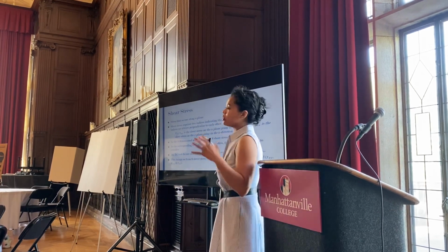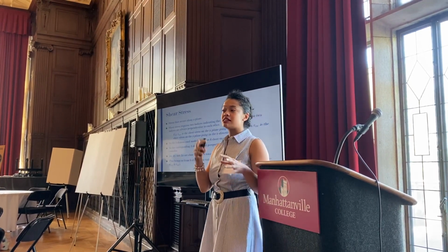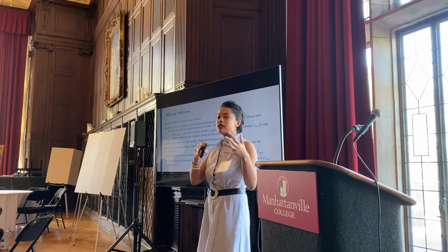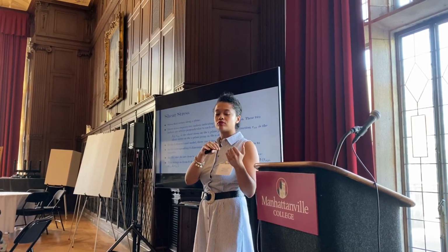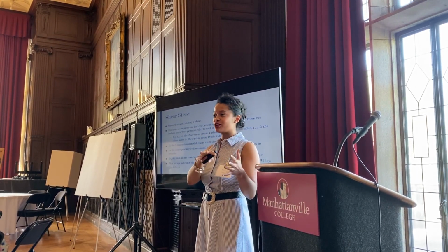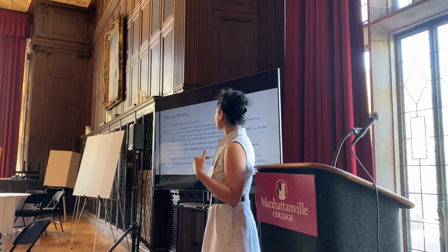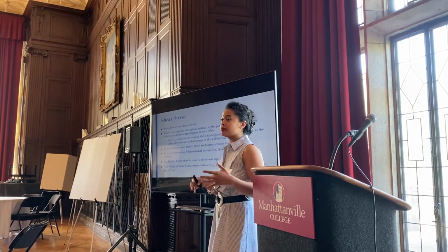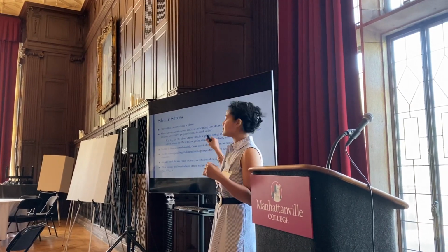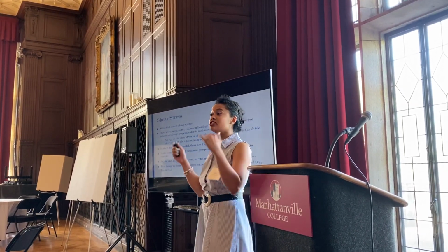Shear stresses occur along a plane. They have two indices indicating where they're going on. One index relates to the plane it's occurring on. The other one is the axial direction it is facing. Since we are dealing with infinitesimally small elements, our dimensions, delta x, delta y, and delta z, are tending to 0.